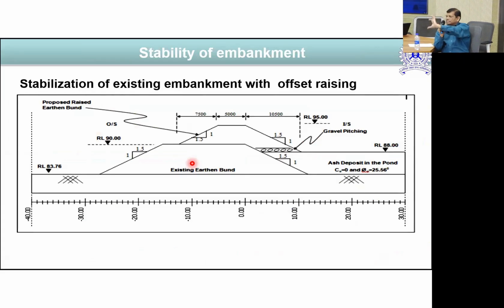Give a better distance. The computer generates 2,000, 8,000, 10,000 circles, depending on what satisfies you. Then it will come up with this is my minimum slip circle, the slip circle which has the minimum factor of safety. So you look at that slip circle and make a decision there.